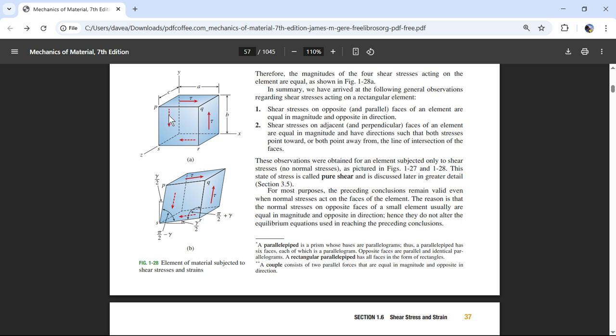And the same thing, we can do that 4 times. Then, when I cut this cube right here, I'm going to be using these 2 stresses acting on areas for my equilibrium. I would just go straight to the free body diagram. I would say this is a force in this direction, this is a force in this direction, and when we make our cut here, I'm going to have a normal force and a shear force.